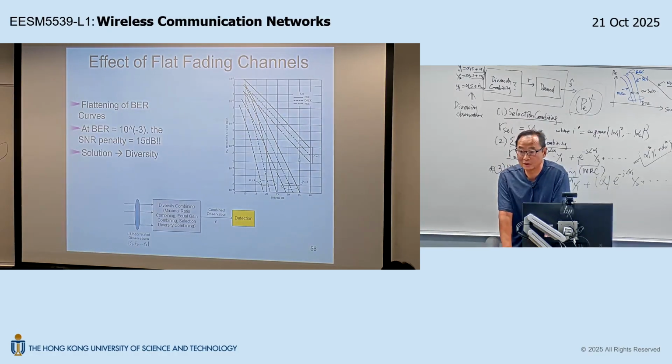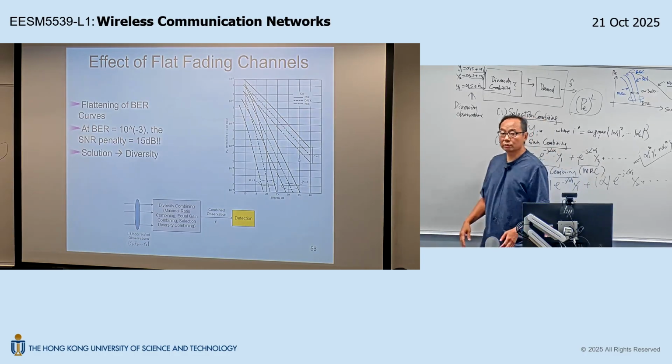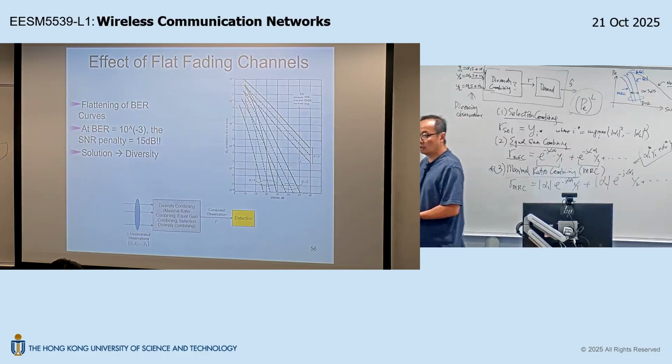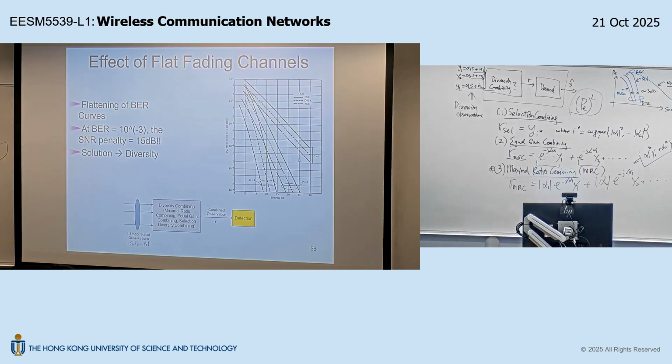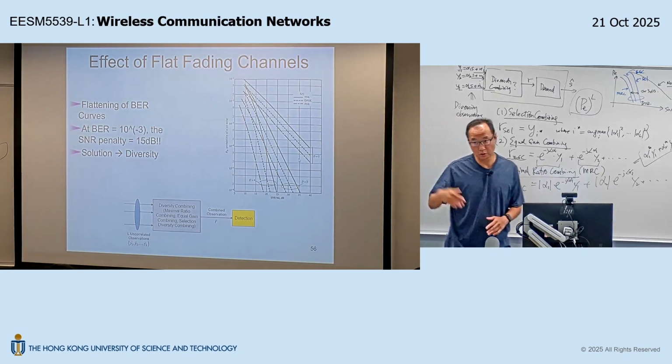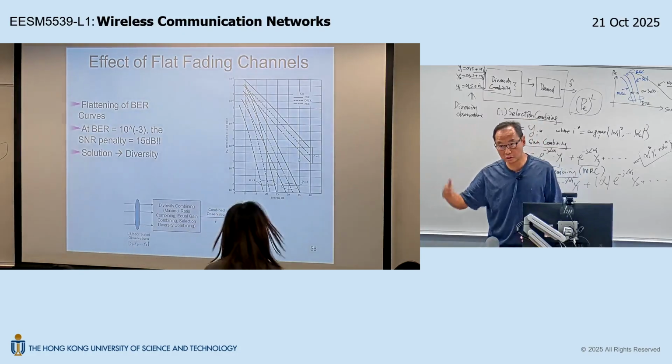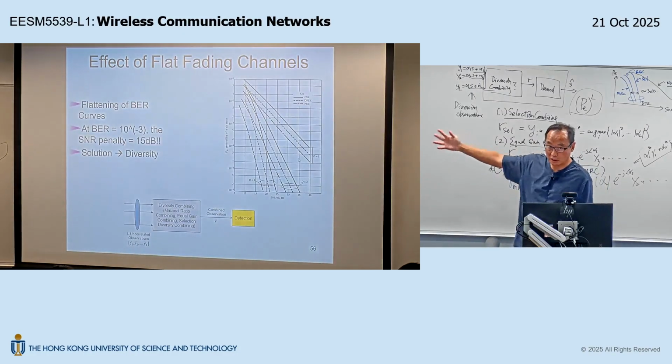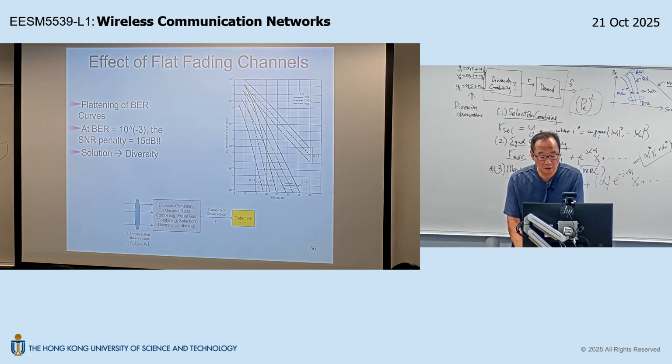Is that okay? Now, of course, I said that was the past. Now, all the MIMO chipsets with the advanced standard 11n are already equipped with MIMO. They are already equipped with multiple RF and ADC chains. So that is no longer an issue, because your baseline solution in the market already has these multiple RF and ADC chains. All right. So although this is 1 page, it took me quite some time to elaborate the solution.